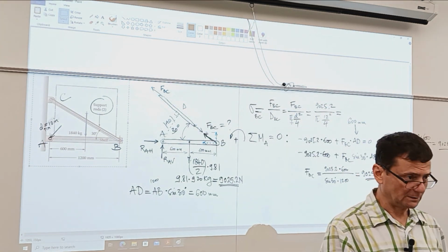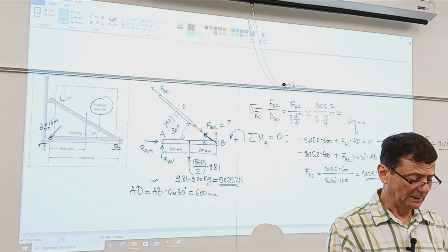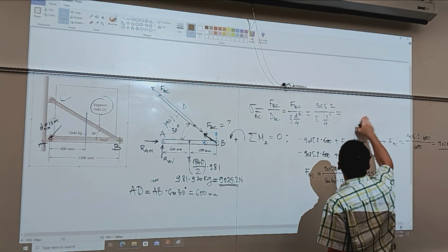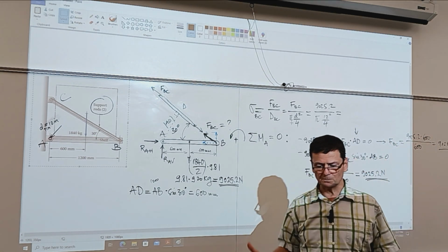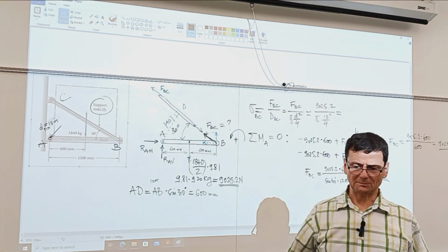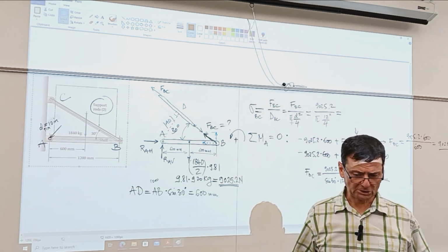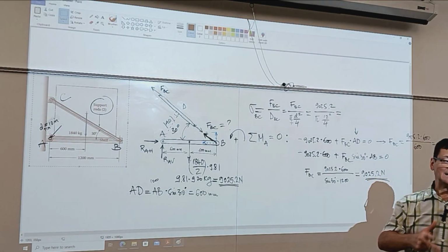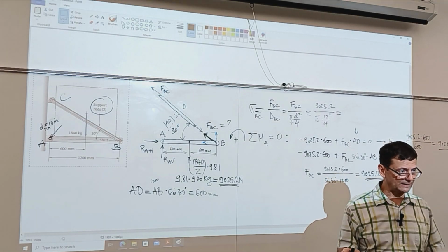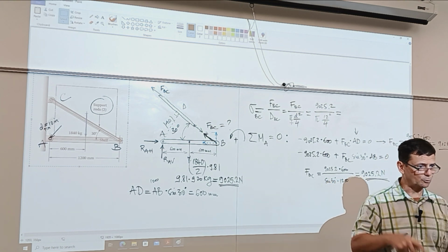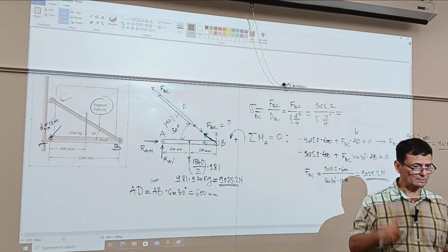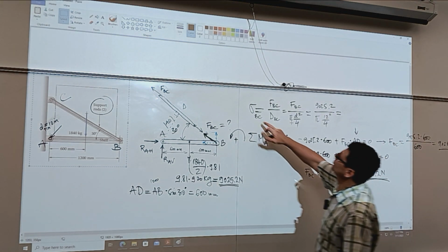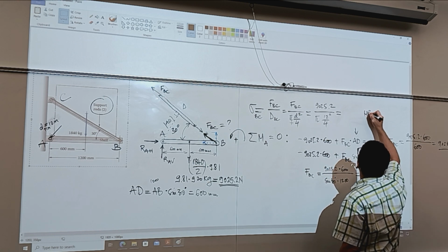So if you work in metric, everything in millimeters and everything in newtons, you'll get the stresses. And so you have newton-millimeter for moments, areas in millimeters squared, moments of inertia in millimeter 3 or 4, depending on what kind of moment of inertia, stresses in megapascals. The equation will be balanced. Okay, you don't need to go through meters. Does it make sense? So remember, all millimeters, all newtons, and all stress is megapascal. So this will be megapascal.